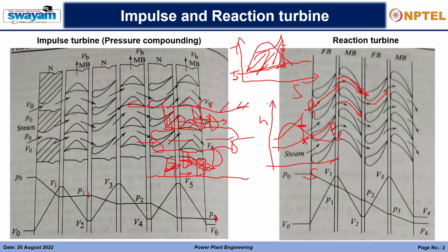So the natural lake water is at a fixed temperature of around 30 degrees Celsius, the ambient condition. And if we need to cool the steam, obviously its temperature should be higher than this. There should be some temperature gap. So it is around 43 to 45, okay, and correspondingly the pressure will be around 7 kilopascal or something like that.